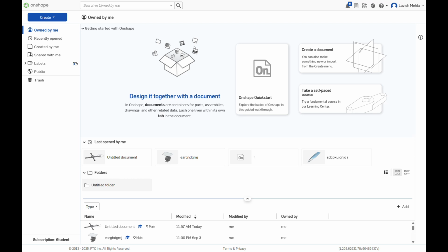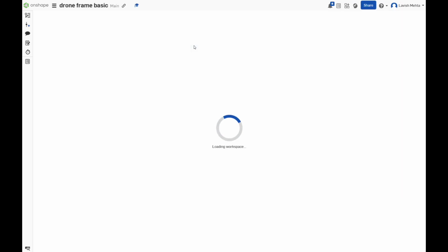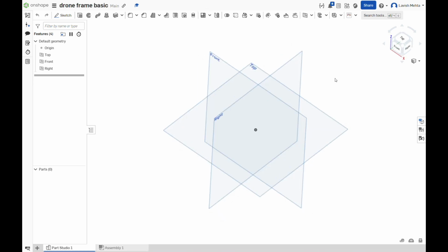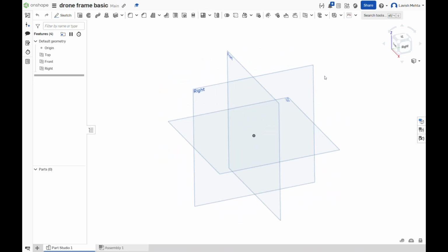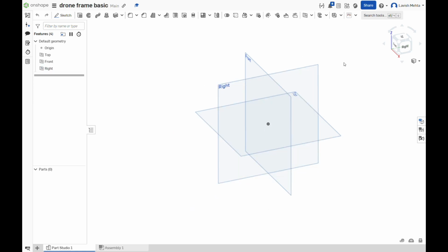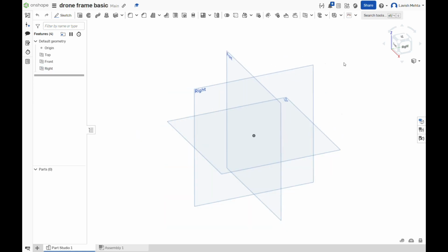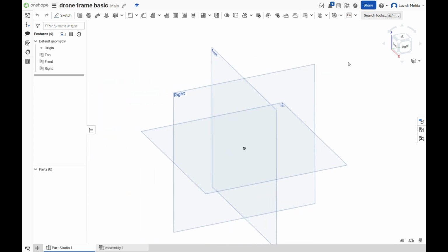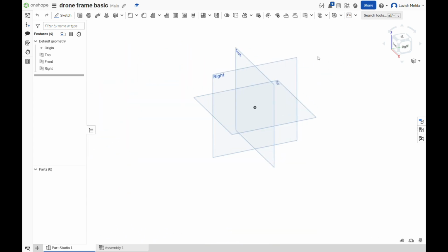Within a few seconds, you will enter the main workspace, which looks like a basic CAD program interface. Right click and moving the mouse will allow you to orbit. Left click will allow you to choose things. Scroll down and scroll up will allow you to zoom in and zoom out. And if you click the scroll button and move, the pan option will be allowed, as you can see. So let's start with our project now.